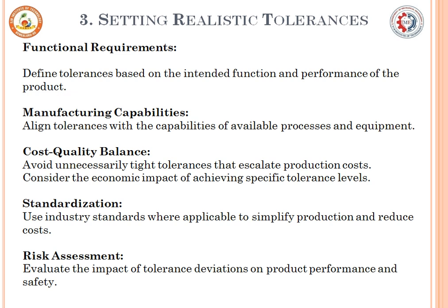Setting realistic tolerances. If overly tight or overly loose cannot be maintained, then you have to go with realistic tolerance. Realistic tolerance is based on the internal function and performance of the product. So the functional requirement is satisfied, and manufacturing capabilities are going to be matched with the right tolerance. So the cost-quality balance is going to happen.